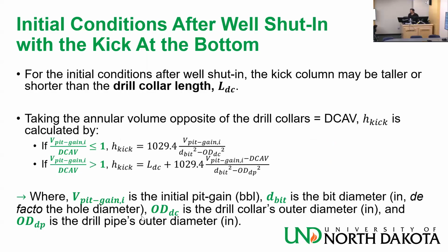In the field, like this app, it records the height of the kick, and I find out that from my calculation, it's almost the same. Is it also like that? Well, the app assumes an EOS model for the kick. But how do you know, you are never really sure what kind of fluid you are dealing with.